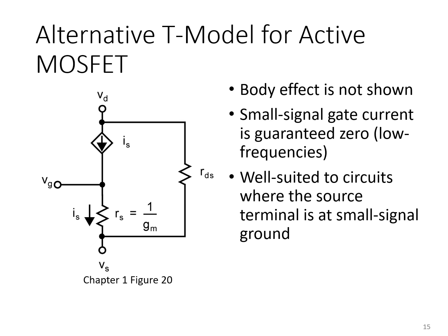Just a reminder that you can also have a low frequency small signal T model for the MOSFET. It looks like this. Just one quick point. Again, I assume this is all background knowledge for you, but just a reminder, not to be confused by the small signal model, wherein it appears that the gate voltage is somehow connected to the channel, and therefore current can somehow flow from the gate and then out the source or drain. That's obviously not the case. Just from the physics of the situation, the gate is physically isolated from the drain and source, so you can't have DC current certainly flowing this way.